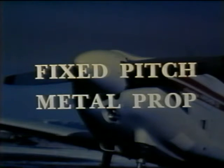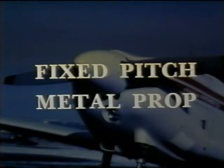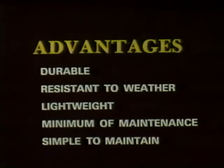Although wood props are still being manufactured, most low horsepower aircraft use a fixed pitch metal propeller. These are usually manufactured from a single piece aluminum forging that has been shaped by machining and hand grinding to a propeller of the desired design. A fixed pitch aluminum prop has the advantages of being durable, resistant to weather, lightweight, requires a minimum amount of maintenance, and is simple to maintain.